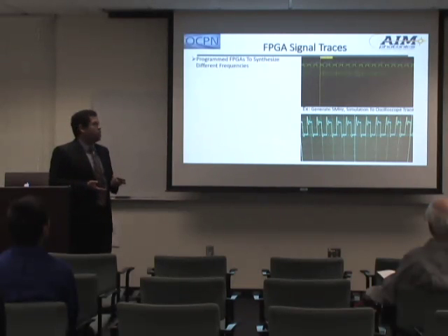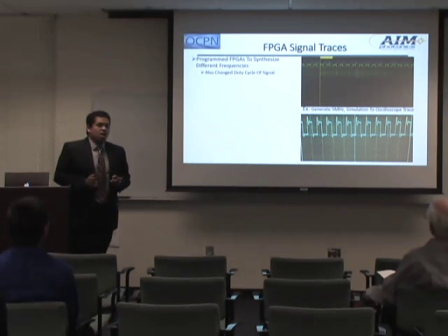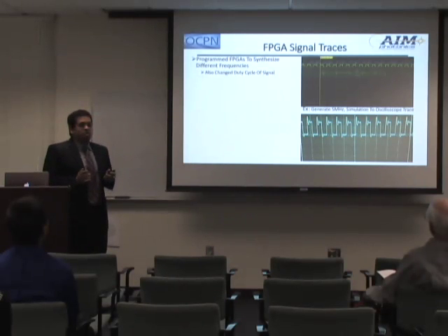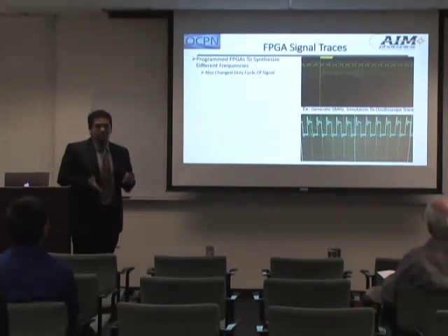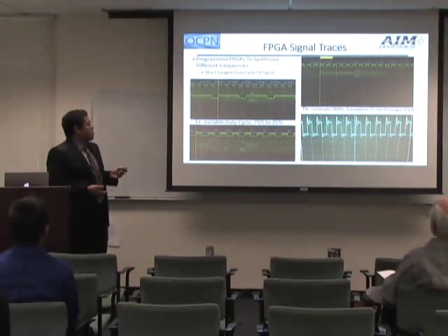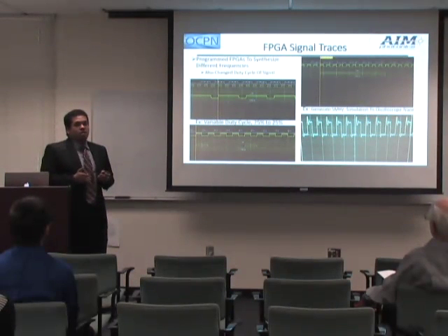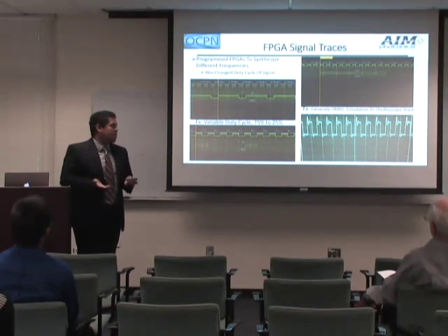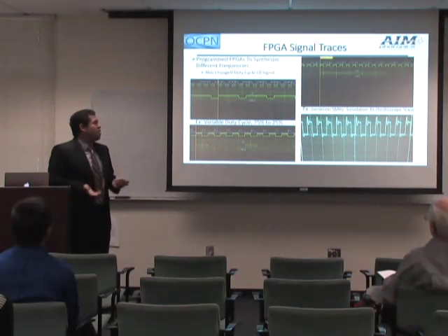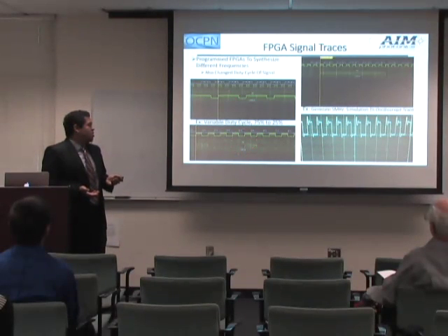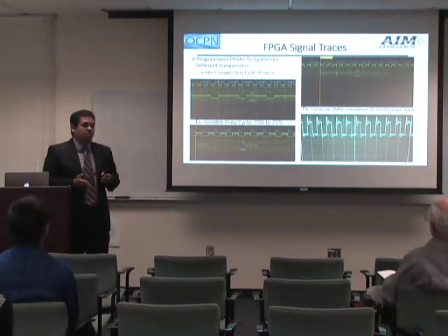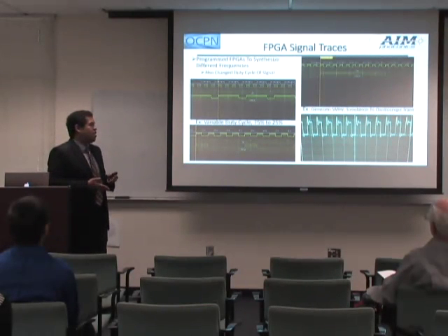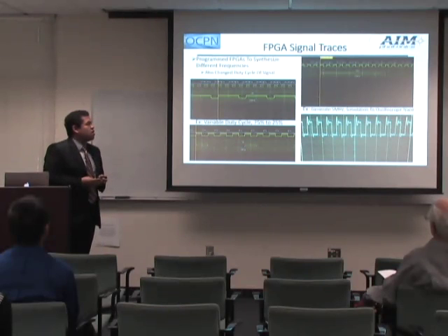Another thing that I've also worked on is changing the duty cycle of the signal. The duty cycle basically indicates the amount of time that the signal is left in an on period versus how long it's left in an off period within its natural cycle. These two are simulation traces where I've used a standard 50% duty cycle wave. So in its natural frequency, it's on for half the time and off for half the time. I shifted it so that it would be 75% on the top and 25% on the bottom. Changing the duty cycle can actually affect the power consumption of the device as well. It's just something that I've also worked on.